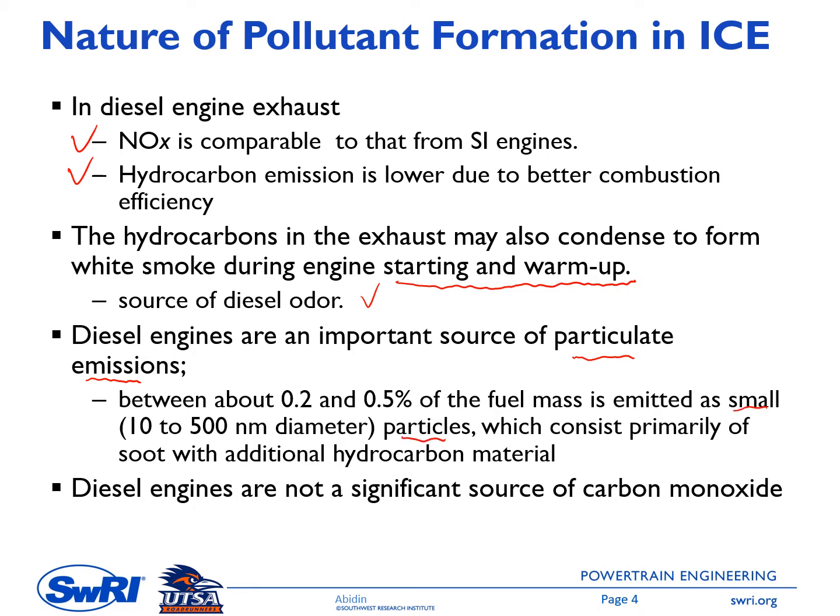So small particle with the size between 10 to 500 nanometer in diameter, and this is a soot, and it has also additional hydrocarbon in it. Diesel engines are not a significant source of carbon monoxide, and this is primarily due to lean mixture combustion.